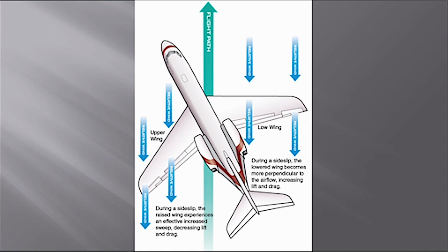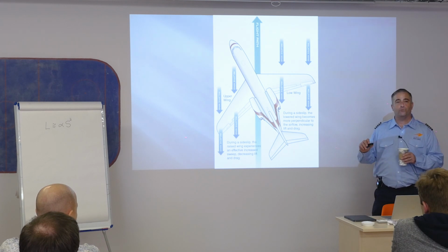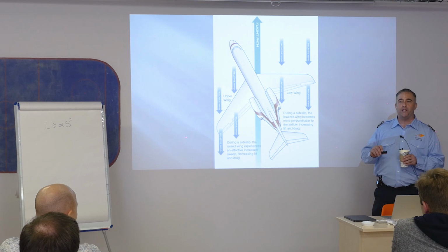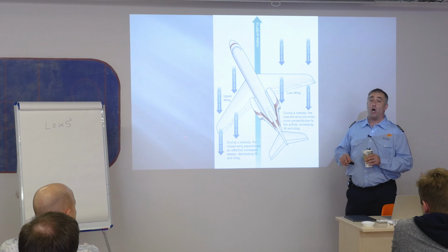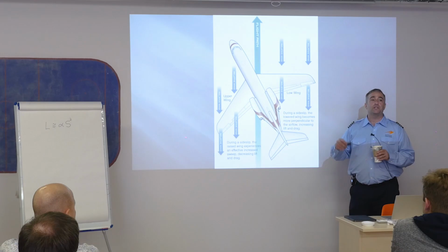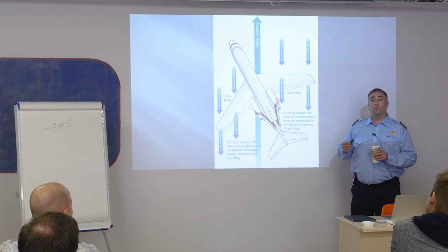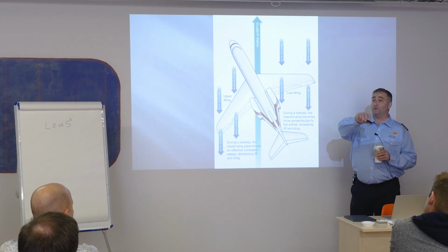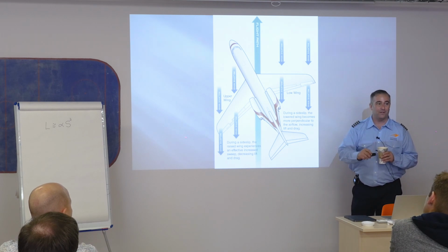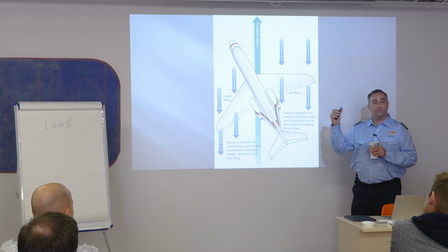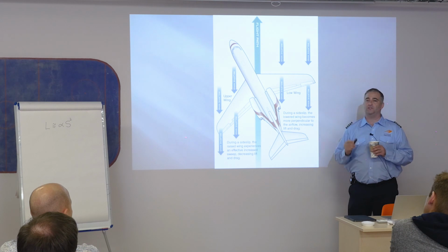Now, Jepsen gives me a real quick snapshot of swept wings and how I can appreciate it. There's so much more going on with these airplanes. Plus, they have something called a yaw damper, which helps us avoid any type of uncoordinated control. With a yaw damper, if I apply aileron control, the airplane automatically applies the appropriate amount of rudder. If I have a side gust from some sort of turbulent condition, the airplane will automatically adjust the rudder.